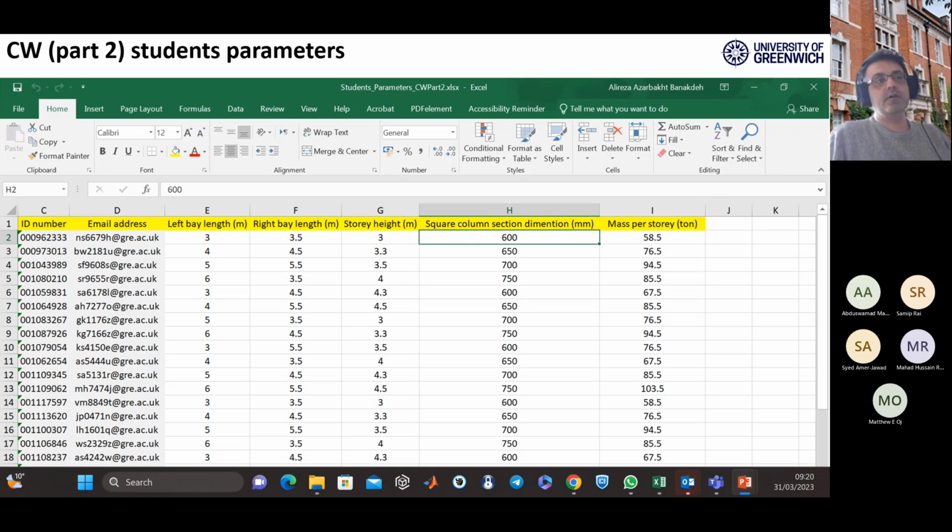First of all, you cannot convert ton to kilonewton. Ton is for mass, kilonewton is for force. Newton will shake in the grave if you do that, because you know the Newton law, force is mass times g, right? So, for example, if you have 1 ton mass